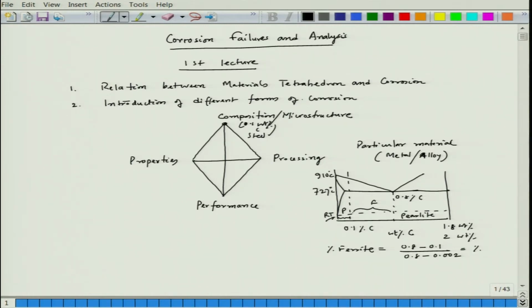So, if we see the microstructure, the microstructure would have some pearlite at the triple points, otherwise mostly ferrite. So, this is ferrite, we call it alpha iron, and this is pearlite. Pearlite is basically a mixture of alpha and Fe3C, which has a lamellar structure. This structure can form if it is slowly cooled from austenite temperature, beyond this particular phase boundary between alpha and austenite. This is austenite.